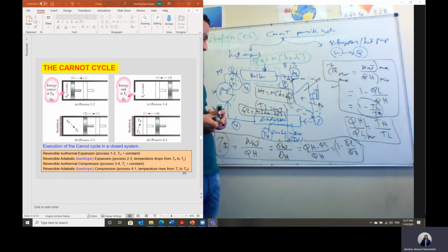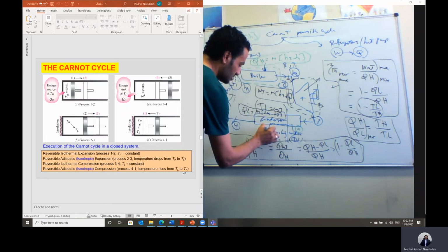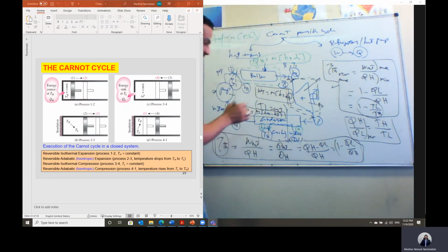And in some cases, he may give you the condition of the cooling water instead of steam at state 3 and state 4. Let's say we have cooling water coming in at state A here, and here it is leaving at state B. Okay, I can give you the condition for A and B. Then we can say Q dot low, which is the heat absorbed by the cooling water, should be the same as the heat rejected from steam, from state 3 to state 4.